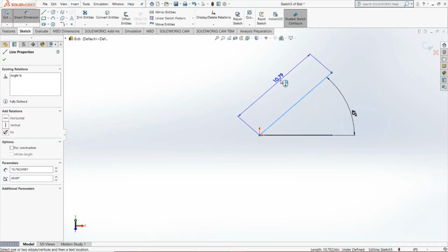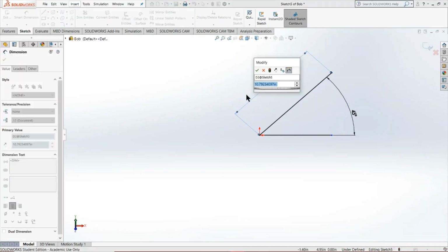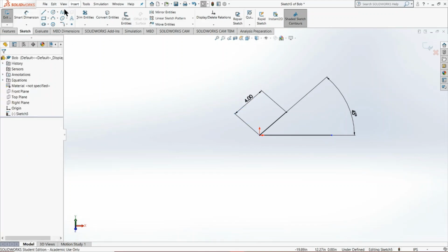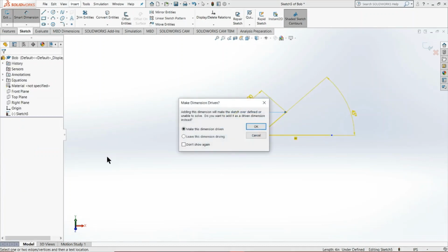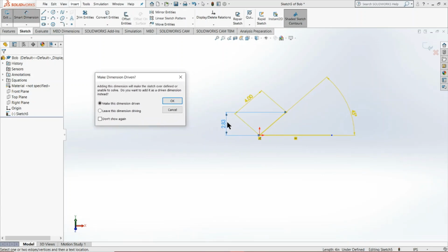And I'm going to show you how not to use this tool. So say we want something that is 4 inches long. Boom. Now what I'm going to do is create this error. And if you may guess why, it's because we tried to augment one more dimension than is possible. By that I mean we already have a set hypotenuse of 4 inches. We already have an angle of 45 degrees. So changing this value by any extent will actually augment the trigonometric ratio that we already have in place here.